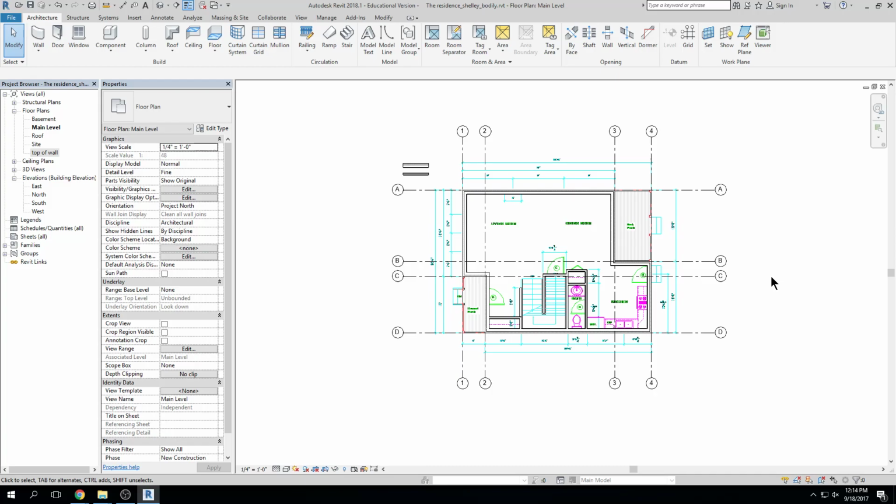Great. We link in our CAD file, we save that, we create some wall types, we start drawing walls. Once we have a few walls established, you think to yourself, okay, let's establish a grid system, so that we keep all of our bearing walls and our bearing lines straight and everything makes sense. We establish a structural grid, okay? So that's the way you're going to start a project, right? Your assignment, you're going to start like this.